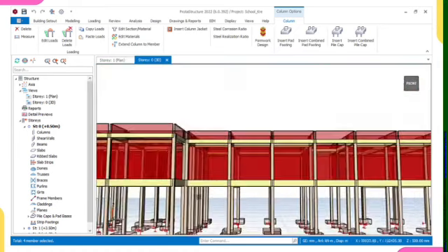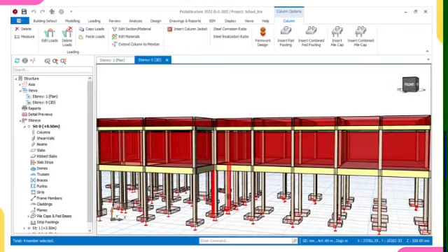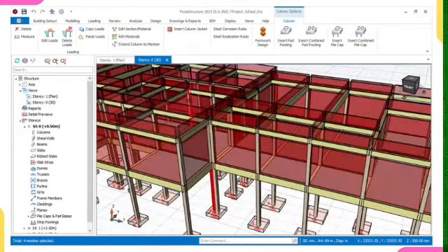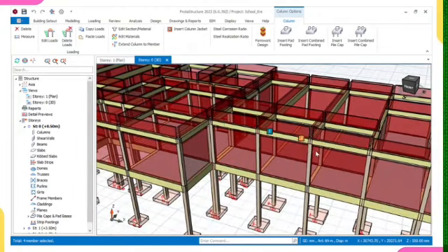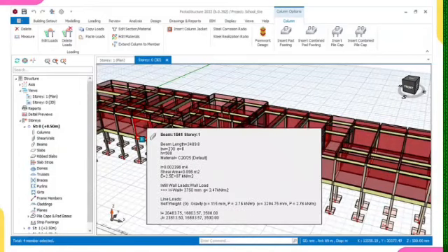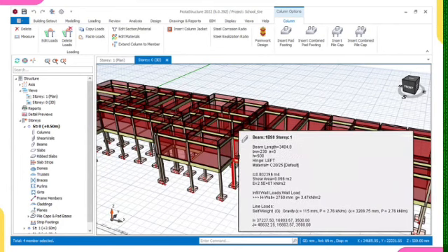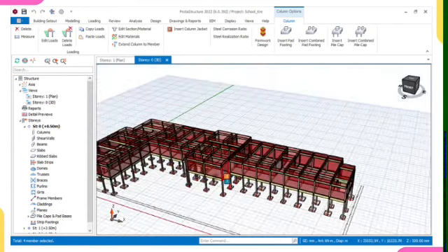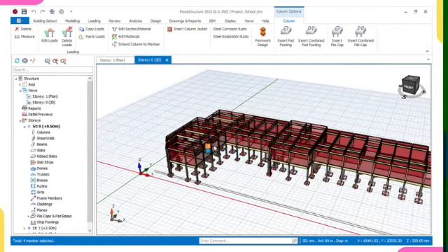But you see, listening to the voice note, I'll say drop, so that you understand everything more. We do not include settlement joints because the buildings are of the same height. Assuming that this part is a two-story building, while this part is a one-story building, that means we will include a settlement joint. And the settlement joint starts from the foundation level. But get the course. Everything is well detailed and explained in the course.